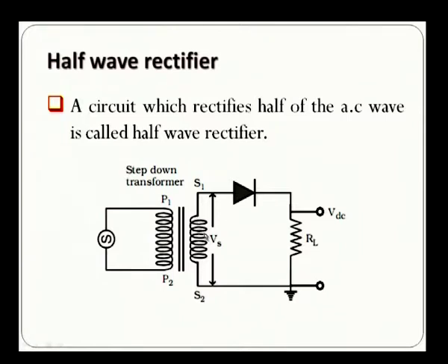As it is written, the number of turns in the secondary coil is less than the number of turns in the primary coil. So, the voltage is reduced. When we have a look at the diagram, especially the secondary coil, it is connected across a load through a single diode, and across this load we measure the voltage. This is the ground connection, which is a common connection for many of the parts, and here we measure the voltage variation.